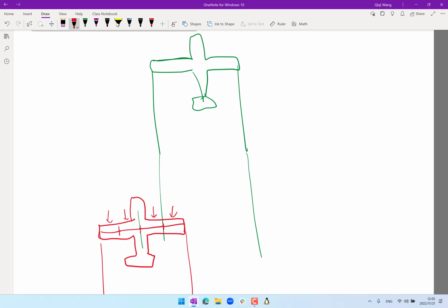So that is a way to roughly estimate how much induced drag you're going to have by computing the downwash. If you want to do it more accurately, you may want to split the wing into even more segments and do the accumulation. Does that make sense? That's a way to figure out how much induced drag the whole system has. All right, good.